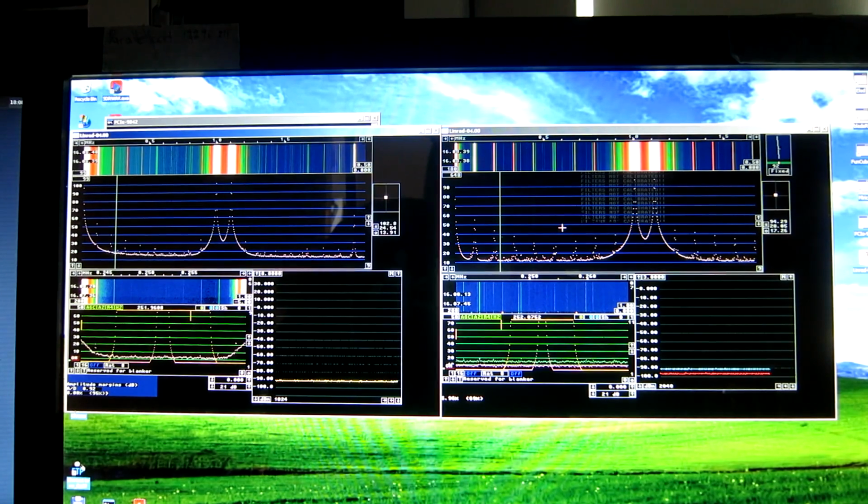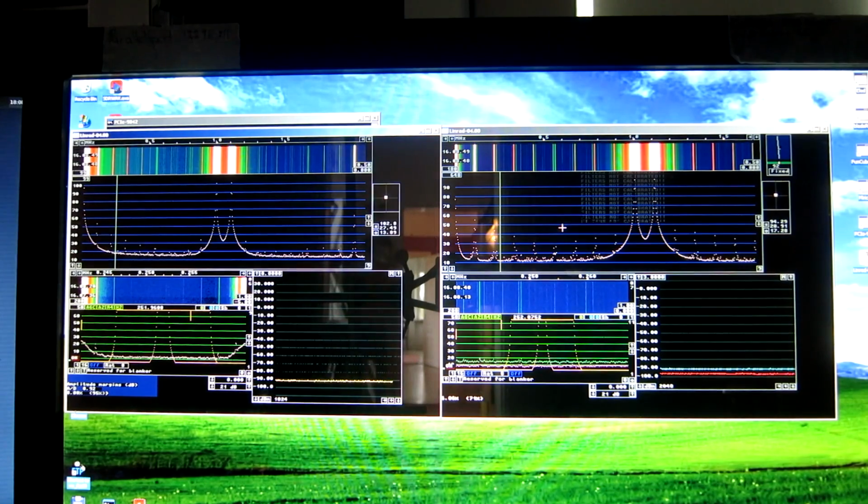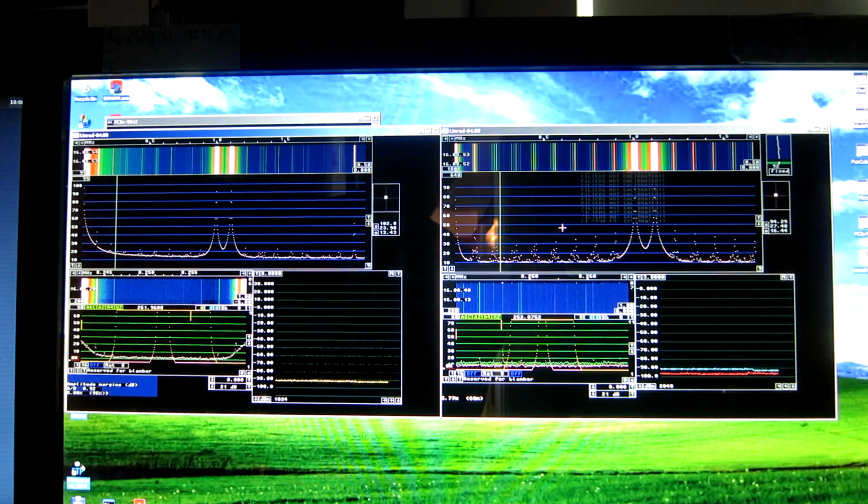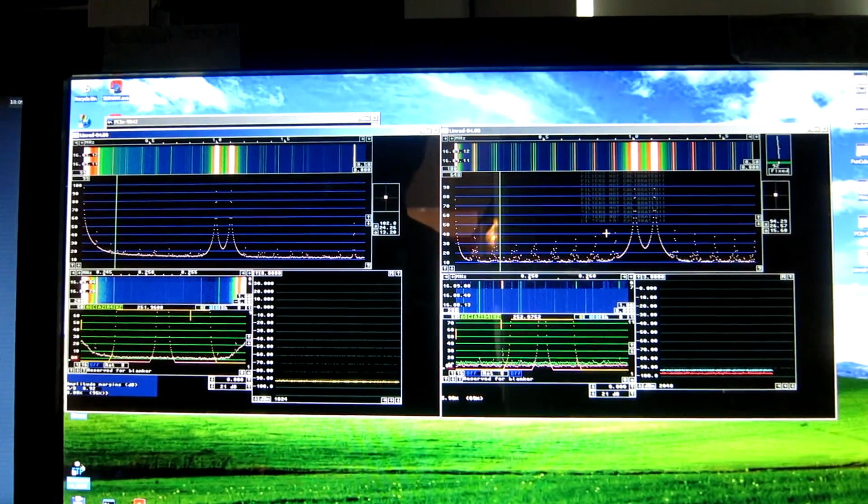The generators are both set to -10 dBm, and I will step them down now in steps of 10 dB. Now it is -20, and what we see here didn't get much better. I mean, if you take the ratio of the signal and this false thing, the signal goes down, but the false signal does not, at least not much.